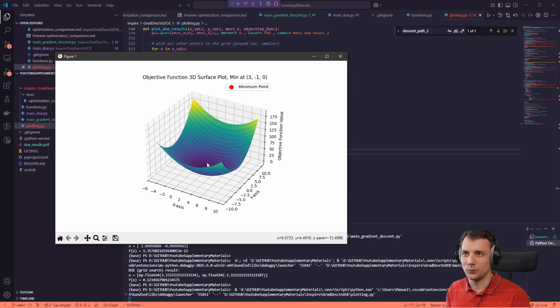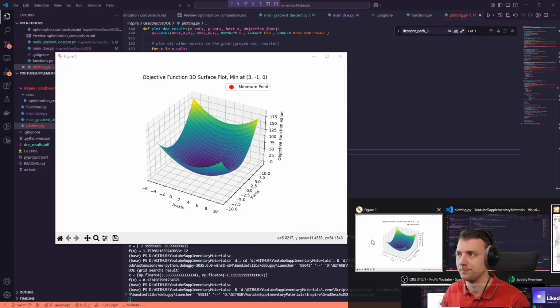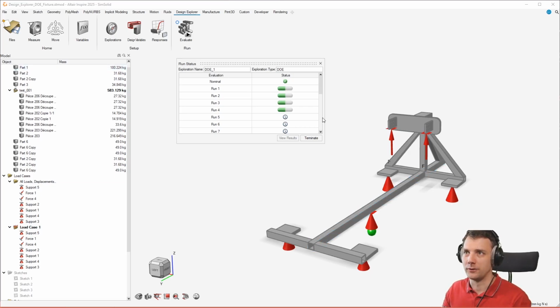And that's why you have to spread the variables or the design values evenly across the design space, so that you have at least a chance to get something which is in the neighborhood of the global minimum, right? So it's all about coverage of the design space, like the different design values. That's why you do something like this.